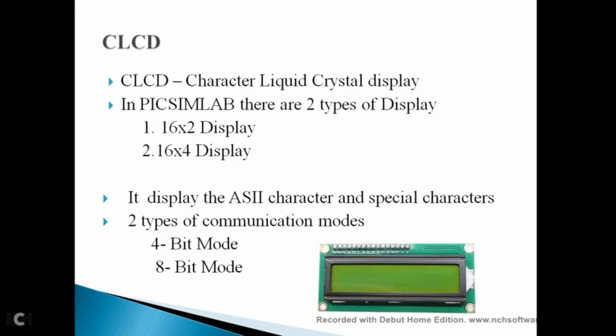The character liquid crystal display. In PICSimLab, there are two types of display, 16 by 2 display and 16 by 4 display, and it also has two types of communication mode. First is 4-bit mode, second is 8-bit mode.